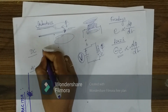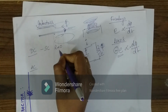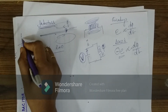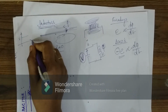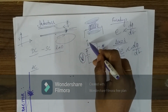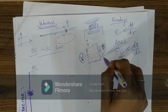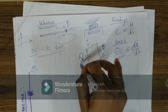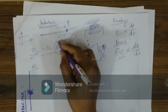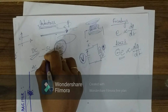For DC circuits, an inductor acts as a short circuit as the resistance is 0. Why is the resistance 0 in DC? Because for DC the voltage remains constant. As the voltage is constant, the current is constant. Again, there is no rate of change of flux, then the EMF is 0. So there is no opposition to the supply voltage in case of DC. No opposition means resistance is equal to 0. If resistance is 0, it behaves as a short circuit.